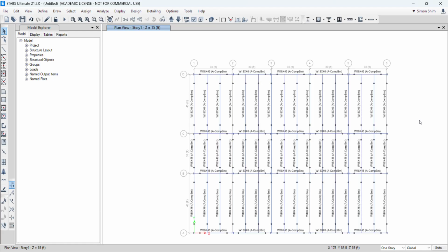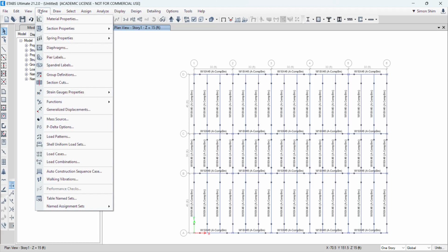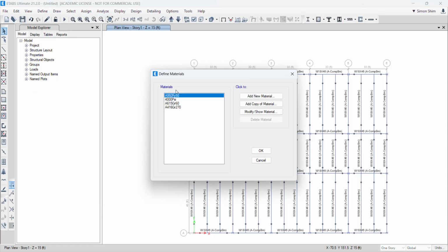All right, now we're going to draw the slab, right? Now our slab is not a concrete slab, this is a metal deck slab. So briefly, let's go check this define. As you know, we need to understand the material properties. Also section properties, all section properties should be associated with the material properties, either steel or concrete, depending on the concrete strength or the steel strength, right?